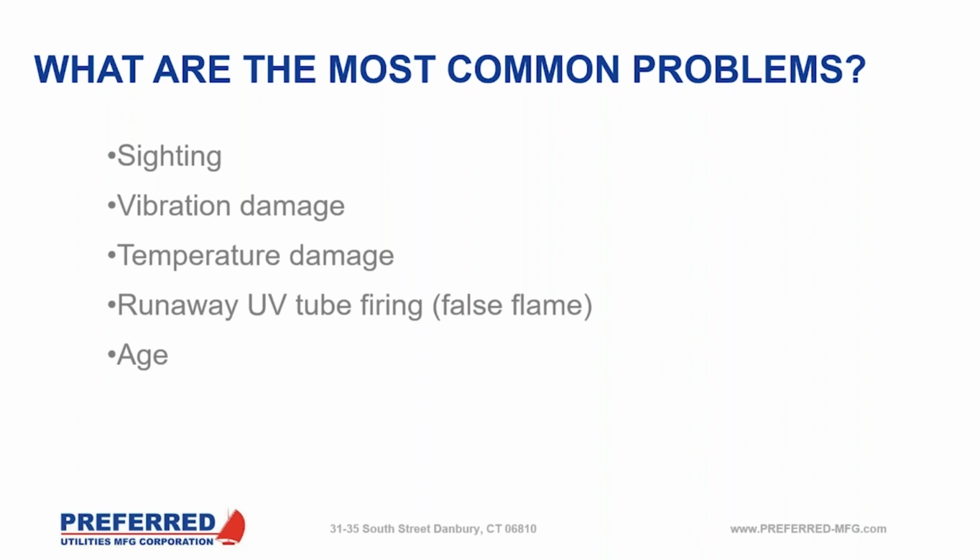Temperature also. Most of them are rated up around 200 degrees Fahrenheit, but a lot of times heat soak or just operating up there at the max for long lengths of time can eventually damage them or even damage the wiring. Most of them are rated extremely high now. We've got better materials for the wires and so forth, but it can still happen. So I always ask the questions if someone's having a problem, when does this occur? How long was it running? Was it up and running for a long period of time before you had a false shutdown? There are some questions that can be asked right there.